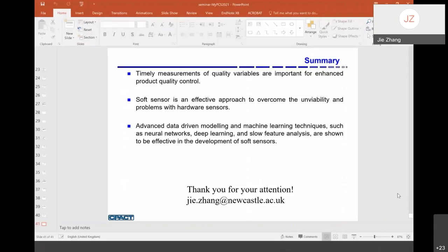Once the data is cleaned, then we can apply this approach. You cannot just get a set of industrial data and apply this approach directly. You need to first check the data from industry, because typically you get those outliers, those missing values, etc. I think the first step when you apply this technique to industry is to pre-screen and pre-process the data from industry.